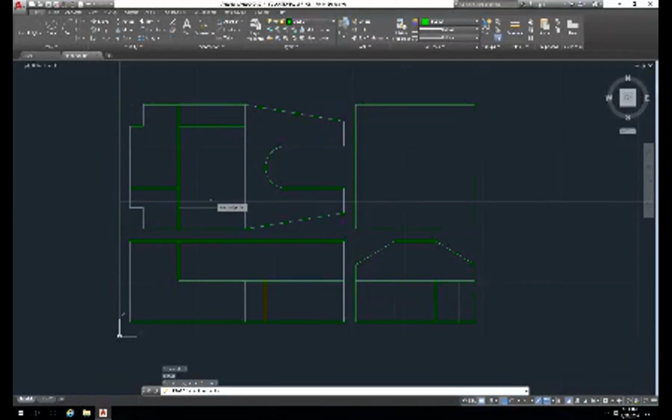Erase. Disappear. Disappear. Okay, gone. So now we need to demonstrate this cutout over here. And we do a line. And let's do intersection. And then perpendicular. It's fine. So now trim from here to here. This little piece. Press enter. Select the line and change the layer. And it's on the hidden layer.